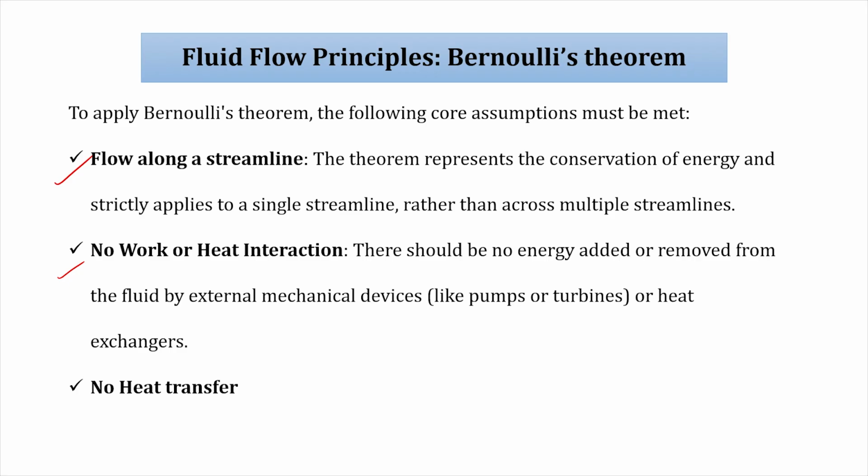Sixth, no work and heat interaction. There should be no energy added or removed from the fluid by external mechanical devices or heat exchangers during the flow. And obviously, if no energy is added or removed, we assume no heat transfer is occurring during the process. During mold filling in gates, we assume no heat transfer. So there are 7 assumptions: steady state flow, incompressible fluid, ideal and non-viscous fluid, irrotational flow, flow along a streamline, and no work and no heat transfer during mold filling.